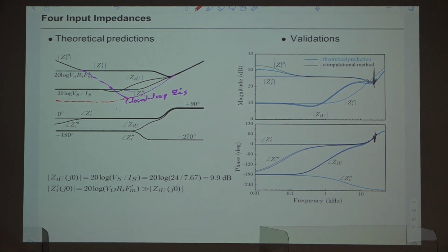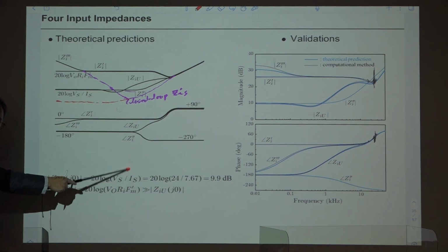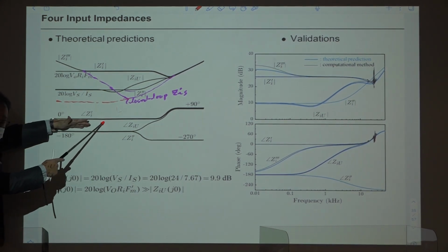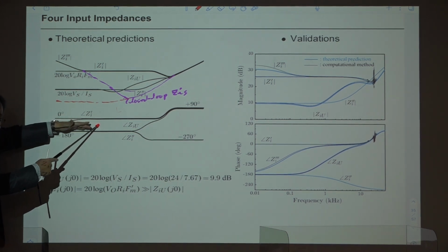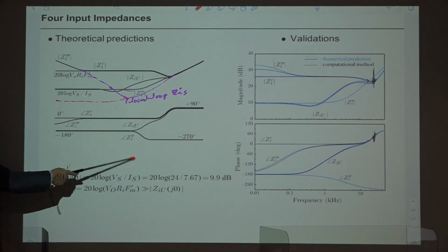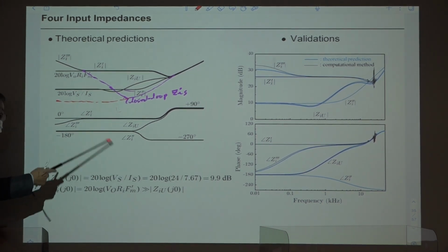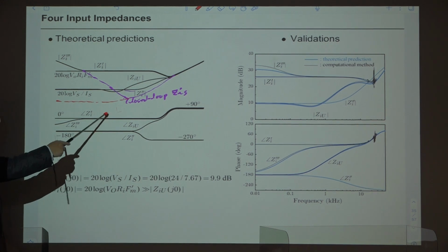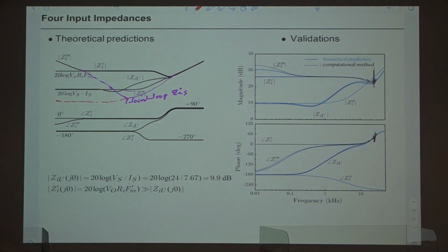So if you have an overlap, suppose the output impedance of this in filter overlaps something like this, this is very dangerous. This is the unstable overlap, right? But this overlap is okay, non-fatal overlap. But suppose your output impedance of your in filter overlaps with this, then it must overlap this thing also, right? So overlapping anything, any impedance here, results in instability, right?